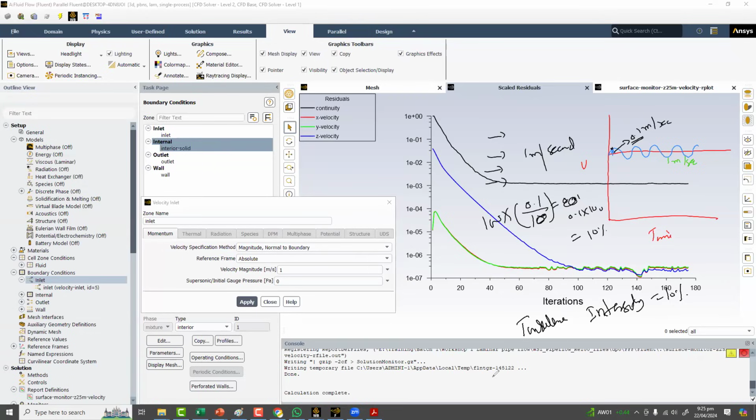Because turbulence is the disturbance in the flow. So now to measure the disturbance in the flow, we use the turbulence intensity, that is, how much turbulence is there. High turbulence means that we will be deviating much from our average flow velocity. And less deviation means that we are more towards laminar flow. This is the definition of turbulence intensity.